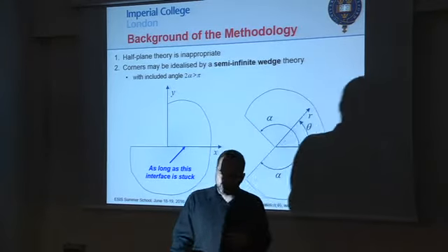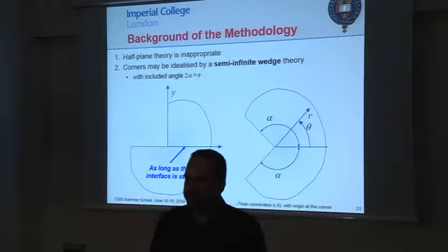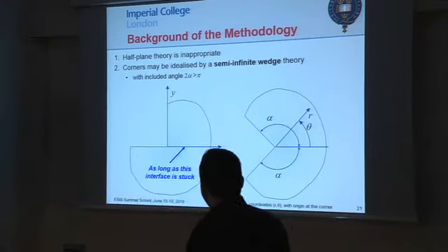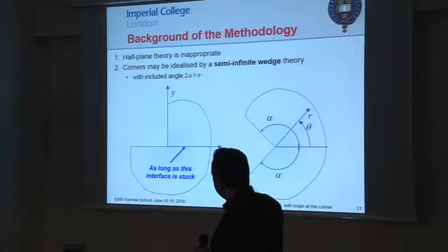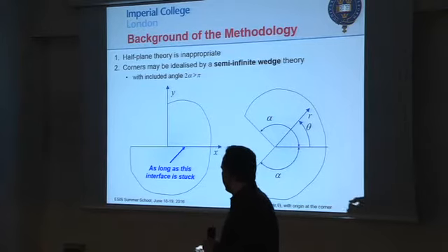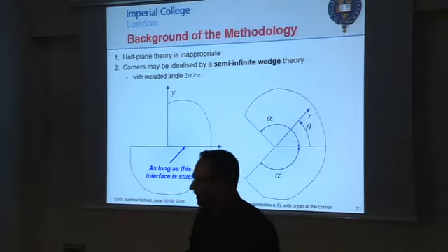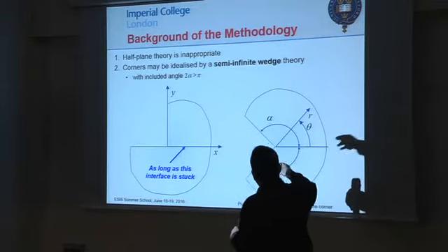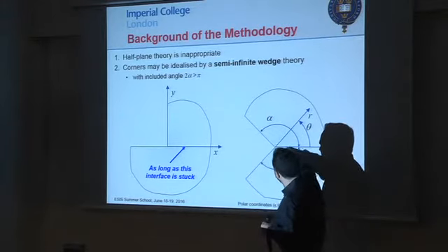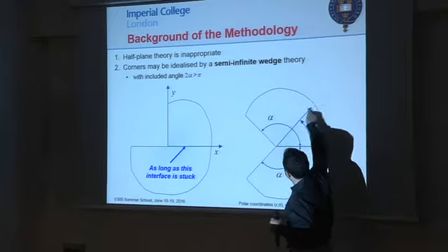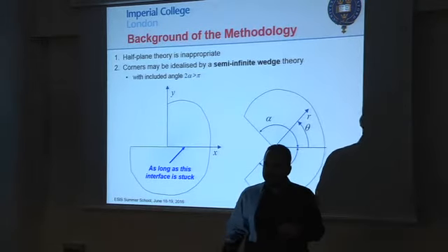It's actually perfectly welded, the same material. So this problem, which is intrinsically a contact problem, becomes the same as a notch problem. All you're doing is rotating this, and in a notch problem you usually start with a problem like this. Here, because we glued this interface, the two problems are identical.